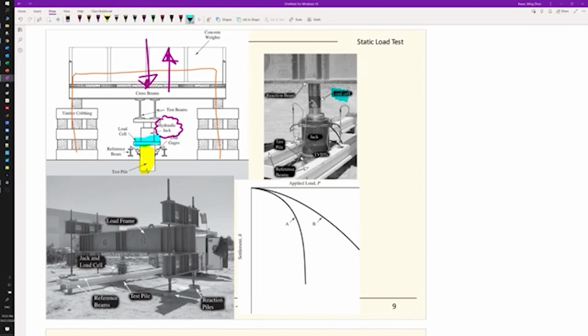So that is exactly what you will be measuring, because you take some displacement for the soil to be fully engaged with the pile, both at the side friction and at the toe. So we need to measure the displacements, and those are LVDTs, a more advanced version of the dial gauge. In the old days, the field engineers would measure it manually, reading the dial gauge, just like what you have done in the soil lab for a consolidation test. You can remember the machine deflection exercise we did together in the lab.